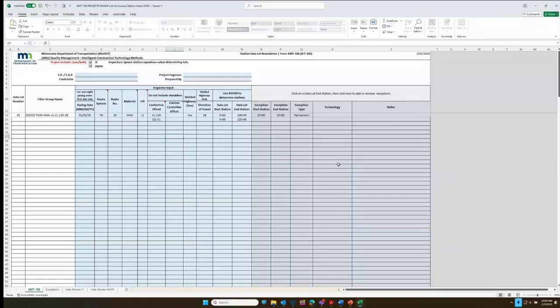And as long as you have a rover out there, either you split it and shoot the hub and then offset it in the CAD program later, or if you just want to, hey, I split it, this is the center, you just take a GPS shot on it, right? And then you can kind of build an alignment from there. That's the main thing that a contractor will need.